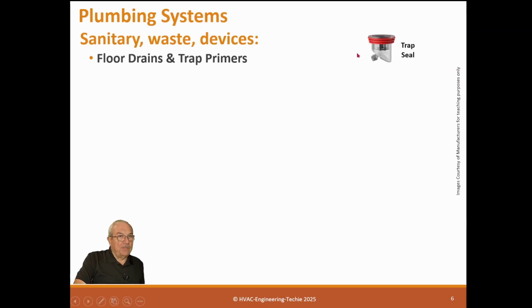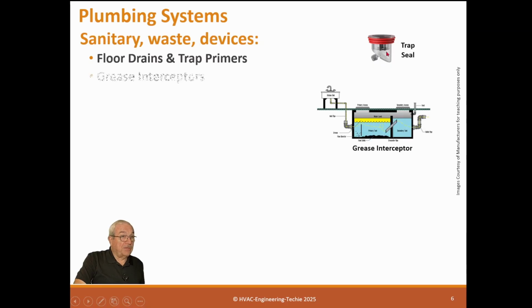And this is a trap seal, and it has a mechanism that basically when it's dry, it's sealed, and when water gets on top, it opens up and lets the water flow. And this is a trap seal, so it doesn't matter if the trap is dry or not, the gas won't come to the space.